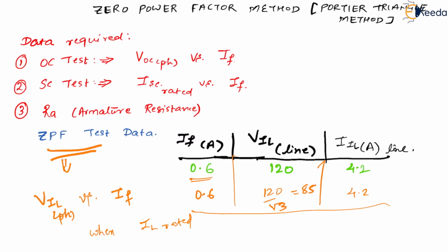And now let us discuss that what is the exact procedure through which we will be finding out the voltage regulation, because for us V full load is not important. Why? Because that will be already provided, that will be given, correct? What is important for us is the no load voltage, correct? EF. So now let us try to see what are the different methods through which we can try to find it. So let us see that.